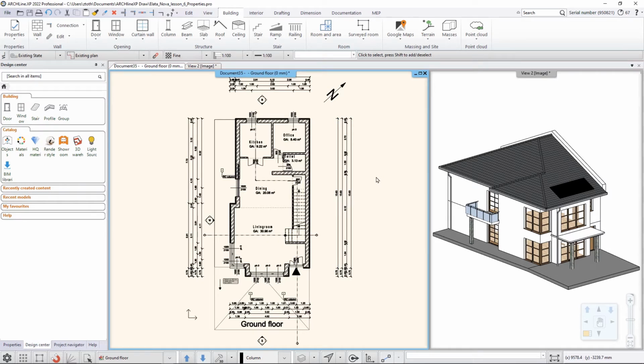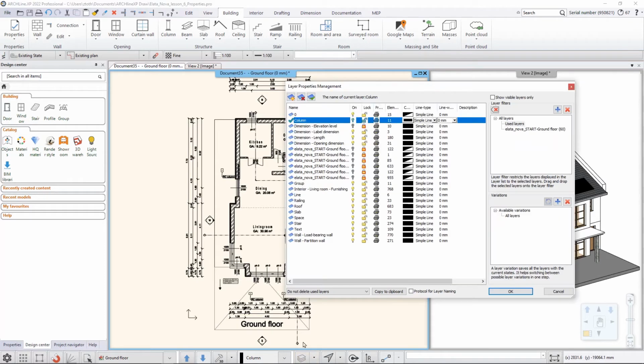Now there is one other setting besides all of those, which is the printing option. This means if I click on this one and see there's a red cross appearing over this printer, this means that whatever is on this layer will be visible, it will be editable, but it won't be printed. Now, this means if I just go to the print dialog and I just see the preview, or I create the PDF file, nothing will be visible that is on this layer.